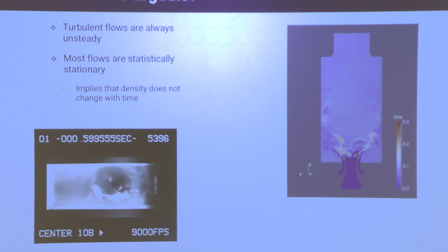that when this mixture fraction, which is fuel to air ratio, right? When this fuel comes in, sometimes it breaks off as lobes of fuel. And it just sits there. And when this lobe of fuel just sits there, very rich, in a high temperature region, it forms soot. And when it forms soot, that fuel after some time gets dispersed, it goes away, and the soot just stays behind. And that's what you see as white regions here.